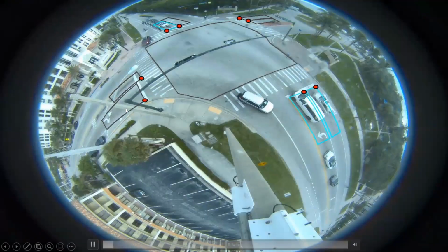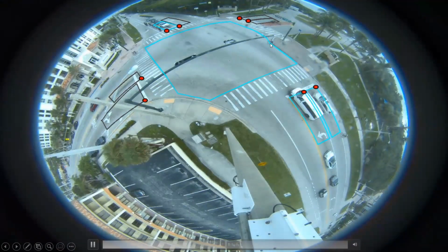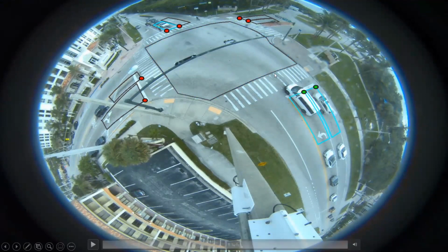Another example here, we're showing a slower user at the top of the screen with a fast user pushing through. Again, the idea here is to exemplify that it doesn't matter how fast you're going for our system. We're providing an extension based on the need or the demand, not based on a simple stop bar trigger. However, we've also seen plenty of bikes position themselves outside of the stop bar. So in those cases, those bikes wouldn't even been given a minimum green, where we're able to provide that amount of time needed.